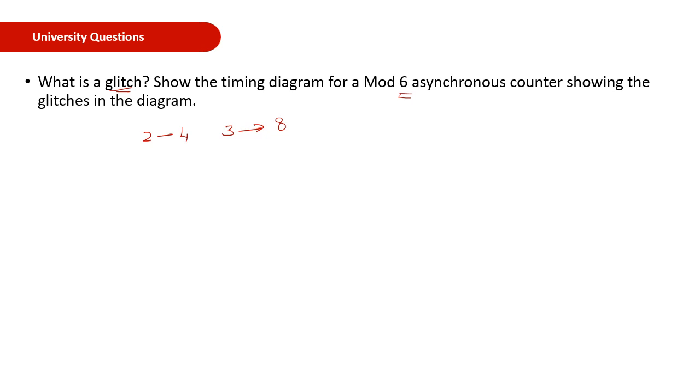So when you design a counter whose number of states is not a power of 2, you have to check the output of your counter, check whether the required number of states has occurred, and when the next state is coming, you have to jump back to the first state.